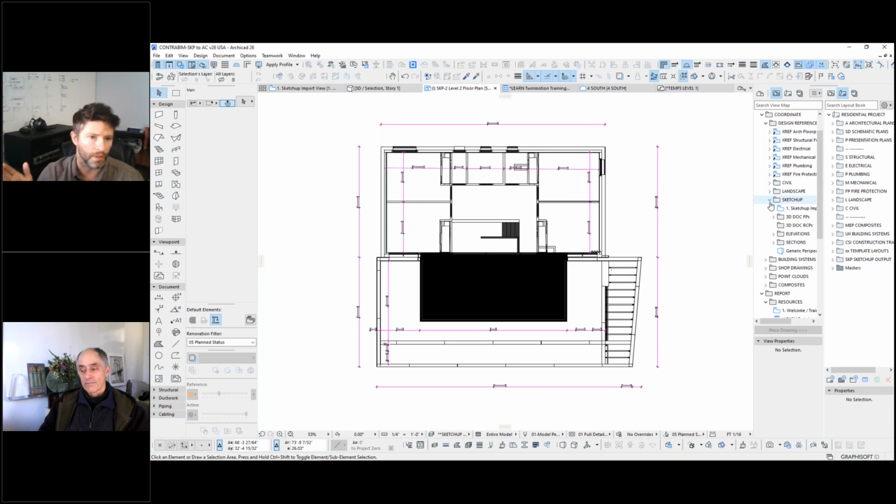Usually the steps I go through are, number one, rotate to make sure that the object is in your XY plane. I'll then look at the project from two different sections and align the exterior walls to the grid line structure that I want to use. And then you adjust the Z elevation to make sure that your finished floors are sitting right, because for whatever reason with SketchUp objects, it never comes in exactly how I want it to be sitting within ArchiCAD. So there's always a process of moving things around a little bit. But once you've got it in place in terms of X, Y, and Z coordinates, cut out some floor plans to reference.